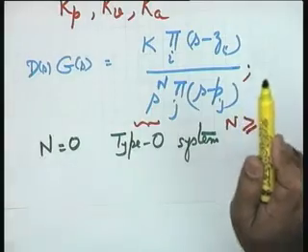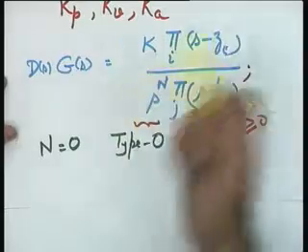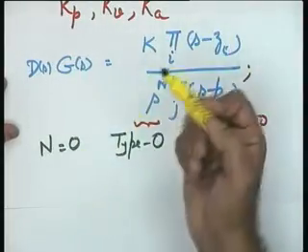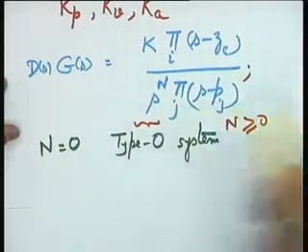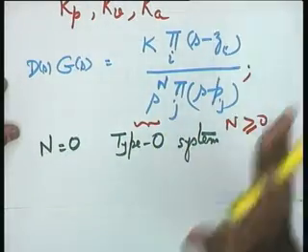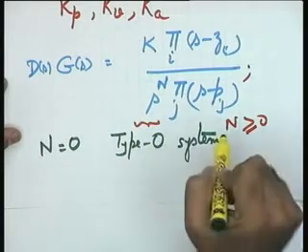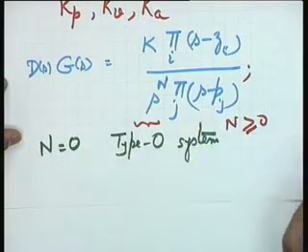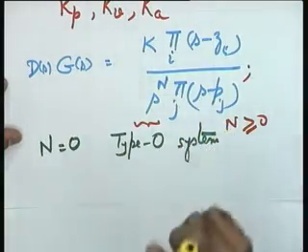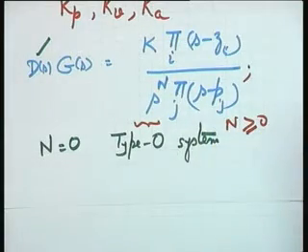You are intentionally introducing integrators, and it will become clear from this analysis why the steady state error to step input will always be 0 when an integrator is introduced. In all the examples we have taken so far, we have seen that the steady state error was 0 whenever there was an integrator. At this point, please note that the number of poles at the origin is the same as the number of integrators in the forward path, and you can control the number of integrators by suitable control on Ds. Therefore, if you require a specific type of steady state behavior, maybe you can realize it by controlling the number of integrators in the forward path.